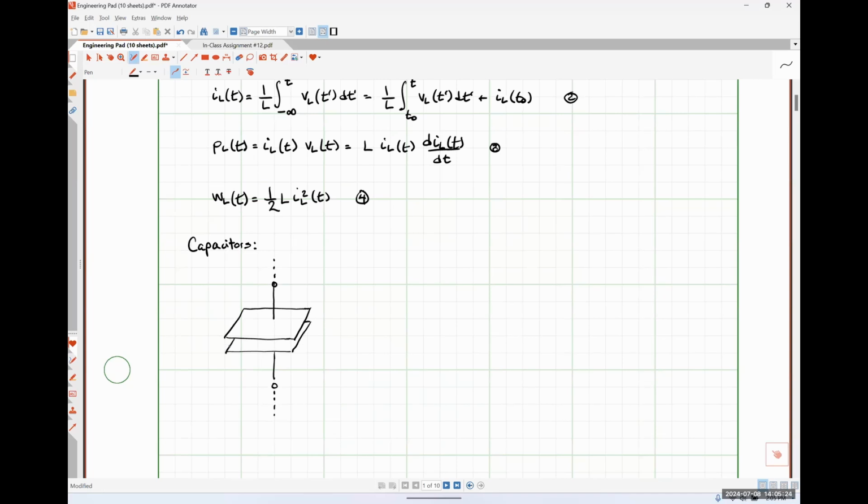So this is an example of what's commonly called a parallel plate capacitor, and the overwhelming majority of capacitors that you could purchase are formed as parallel plate capacitors. Realistically, any two conducting media that are close to each other will exhibit some form of capacitance. But when we place two of them very close together specifically, that's how we form a capacitor like we have illustrated here.